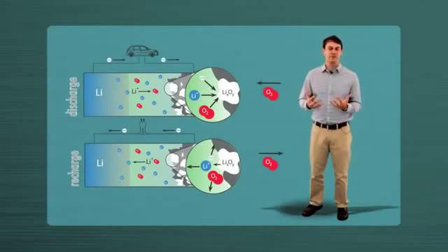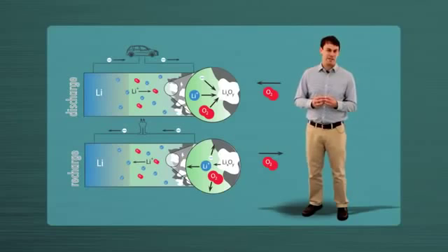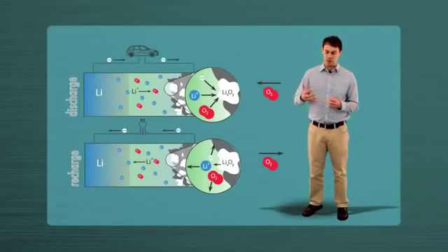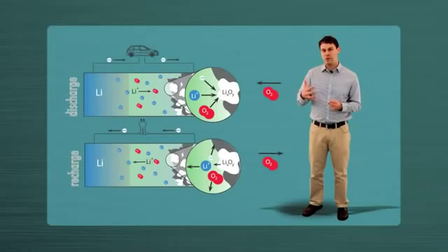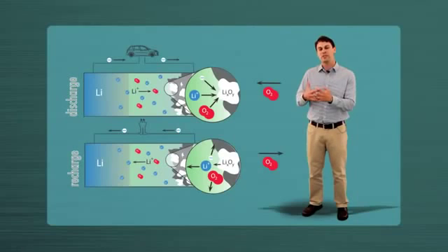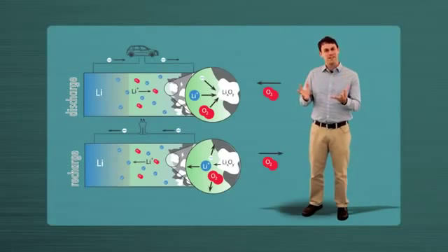So that's, of course, very different from the intercalation mechanism we talked about in a lithium-ion battery, where, for example, in the cathode we had a rigid host where we would intercalate lithium ions into existing vacancies in that material. So here we're making a new phase as we discharge the battery, and then that phase has to go away when we recharge. So that's a fundamentally different mechanism, and you can see that the creation and decomposition of this phase, I would speculate, is going to be a slow process, and to some extent we see that in the rate capability or the power density of these batteries. So that's basically an allusion to one of the limitations of this system.